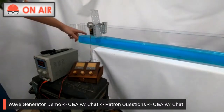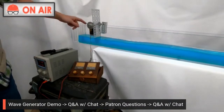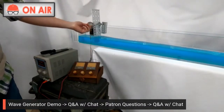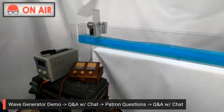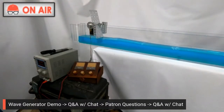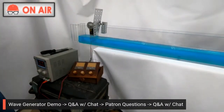The servo itself is geared down with these aluminum gears, and then I have a shaft running from either side of the flume that's attached with a set screw to this hub, and then it just has a big aluminum plate bolted to the shaft, and that gets moved with the servo. And these are all parts made by a company called Servo City, I believe. They build these aluminum, almost Lego parts called Actobotics.